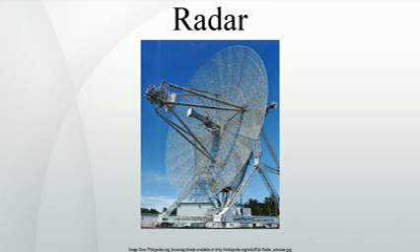Jamming is considered an active interference source, since it is initiated by elements outside the radar and in general unrelated to the radar signals. Jamming is problematic to radar since the jamming signal only needs to travel one way, from the jammer to the radar receiver, whereas the radar echoes travel two ways, radar to target to radar, and are therefore significantly reduced in power by the time they return to the radar receiver.